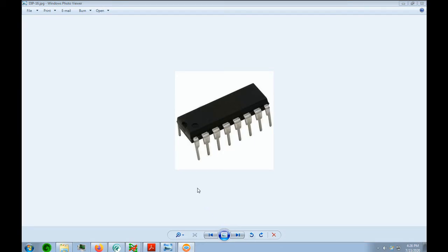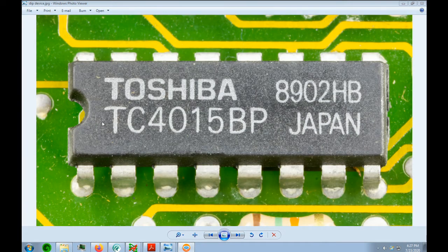In this lesson, we're going to create a DIP 16. It's a through-hole device, and we're going to be using the pad stacks that we created. This is a picture of the device actually mounted into the circuit board. You can see that the pins are going into the holes. They're getting soldered. The green, of course, is your solder mask, preventing you from getting any solder from a pin to a trace, for instance.